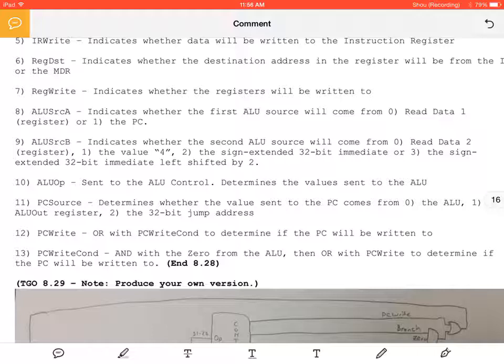And the third one, you're talking about structural data hazards, are particularly in pipelining, what happens if you are trying to complete an instruction where you have not updated a previous instruction's calculation of that datum back to the registers yet. And so multi-cycle gets rid of that by completing each instruction, then completing the next instruction, then completing the next instruction, or reducing the number of cycles per instruction. So those types of hazards are eliminated as well.